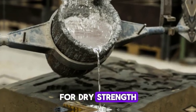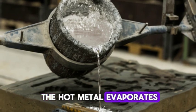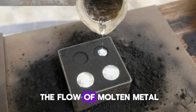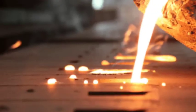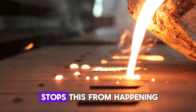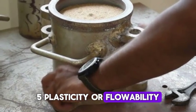4. Dry strength. The moisture in the sand layer next to the hot metal evaporates as soon as the molten metal is poured into the mold. Therefore, the mold wall must not be eroded during the flow of molten metal if the dry sand layer has enough strength to maintain its shape. The metallostatic pressure of the liquid metal causes the mold chamber to increase, but the dry strength stops this from happening.